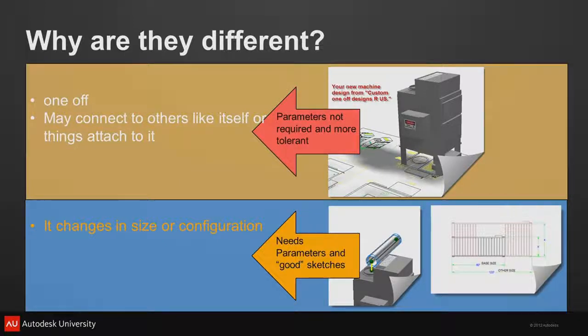So what am I building up to on this, right? So we've got these AutoCAD drawings. Remember, we'll come back to that now. We've got AutoCAD drawings. And we're looking at what do we do with those? How do we leverage them? How do we do anything with them? There's a thing inside of Inventor. I don't know if you guys have used it. It's called Import DWG. So Import DWG allows us to be able to create a part from a drawing.